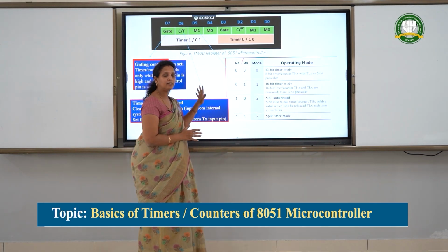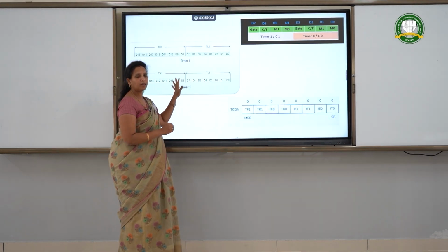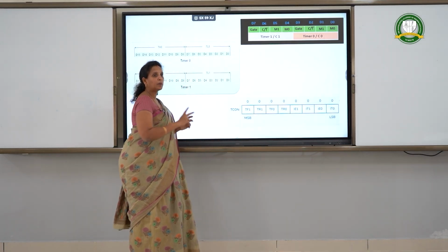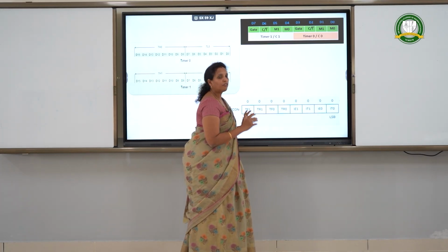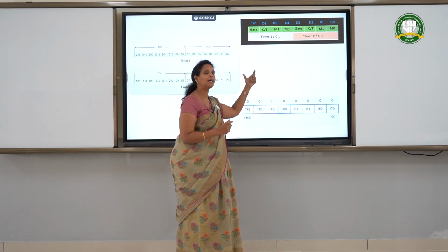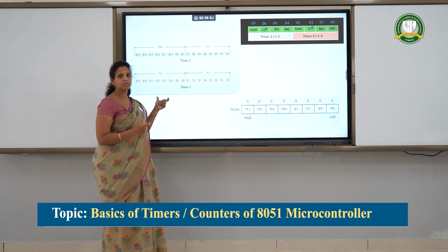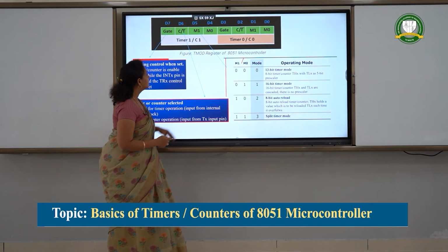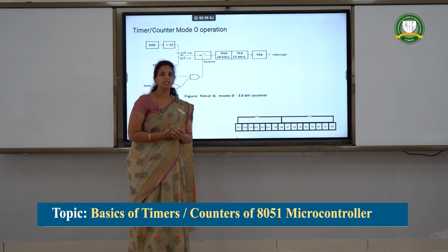As we have studied till now, there are 4 important registers necessary: timer 0 and timer 1, which work with 16 bits, and in order to work with these we need the help of 2 special function registers, called TMOD and TCON. Whenever we write instructions suitably to alter the bits present in TMOD and TCON, based on that the value will keep incrementing and a certain amount of delay will be generated. As mentioned, we can work in any of the 4 modes depending on the application. So now we shall discuss the 4 important modes with respect to their operation and block diagram.